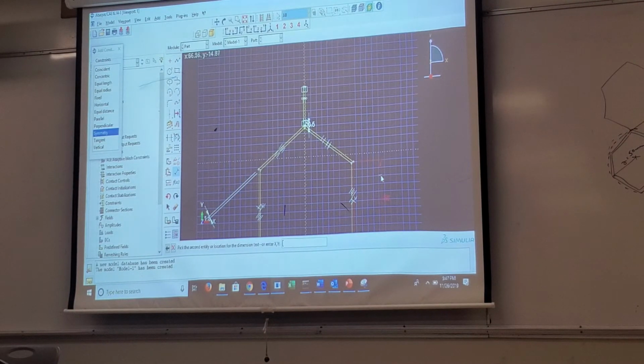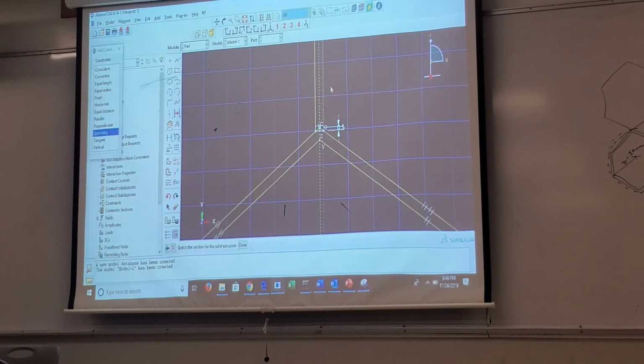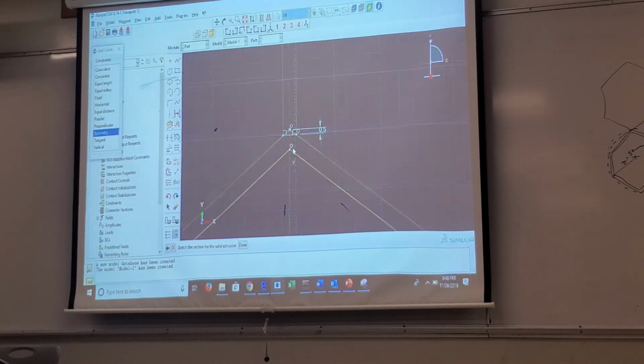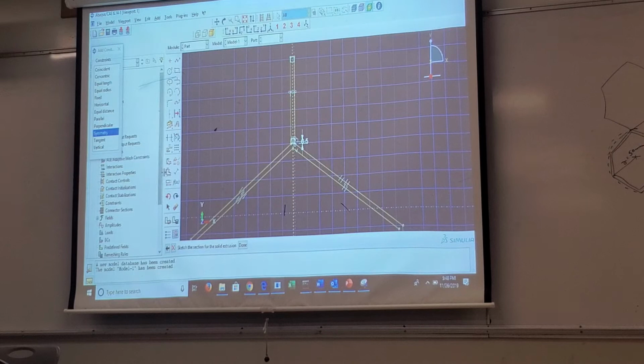Can you go back to how you created the rectangle? How I create a rectangle, I just press this, and then use this button, and then select a rectangle around this center line. Done? What's the point? 0.5? 0.5. What happens is my rectangle was touching almost close to that. So I just give an arbitrary dimension of 0.5 so that it basically clears that surface. Yeah? Let me know once it is done. And specify the length of that rectangle as 25 units.